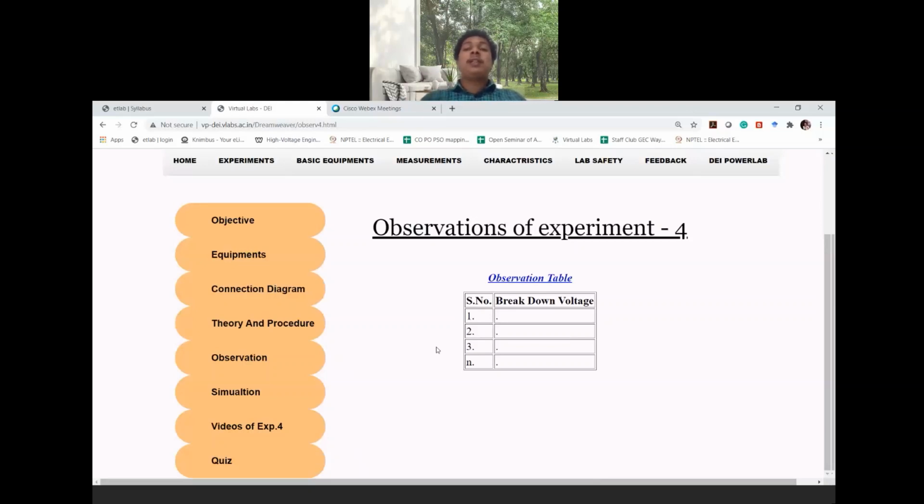The scale parameter represents the breakdown voltage, the dielectric strength or breakdown strength. The shape parameter represents the variance in the samples we conducted. Understood? When your shape parameter is very high, we might not be that confident that the breakdown strength obtained is quite correct. When your shape parameter is lower, then we can say our breakdown strength is nearby our scale parameter. There are also some other standards, where they see whether there is some large variation or not.